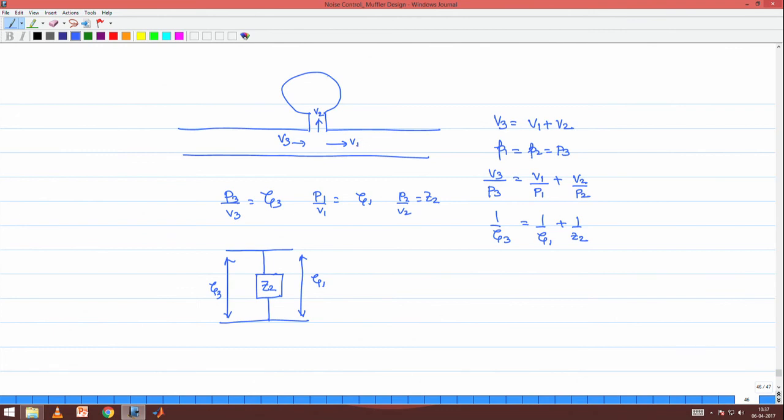See, here what is happening is a standing wave is getting generated. It is not that it is only a travelling wave and it will get reflected. A standing wave situation has already been created, that is why it is a resonator, otherwise you cannot have a resonator. It is only that now we are appealing to the impedance of the Helmholtz resonator and we are tuning the resonance frequencies such that you have a zero impedance in the bypass line. Okay.